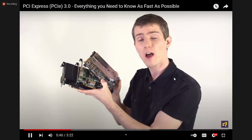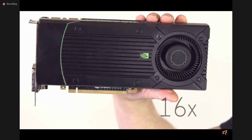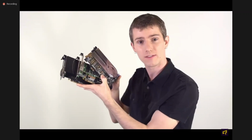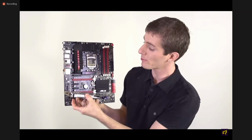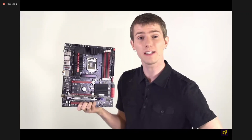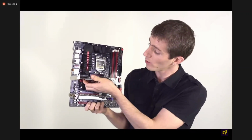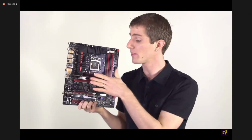All of these types have different slots on the cards themselves and different slots on the motherboard. The cool part about that is that they're upwards and downwards compatible though. Here I am plugging a PCI Express 1x card into a 16x slot. It gets the same power delivery, it just gets less bandwidth delivered to it because that's all a sound card actually needs. And not only that, but I can take this PCIe 8x RAID card and plug it into a PCIe 4x slot. It'll still work, but it will only have half of the bandwidth available to it that it would have otherwise had if you plugged it into an 8x slot.